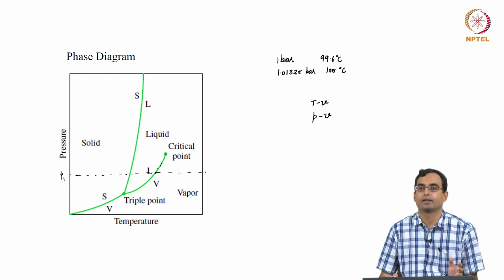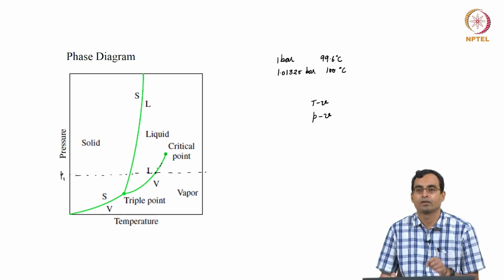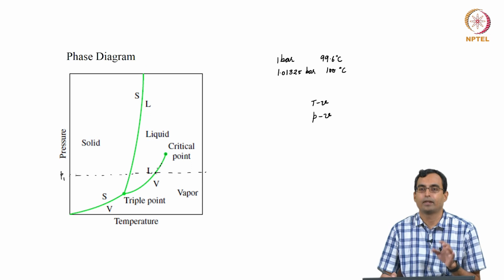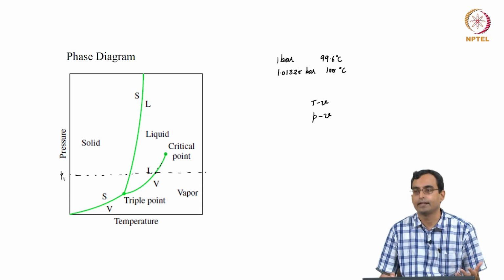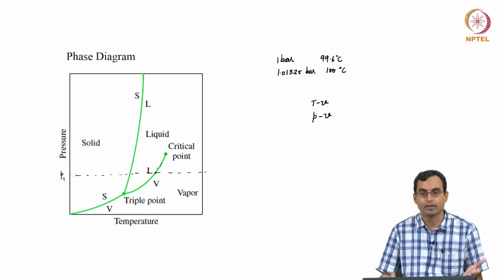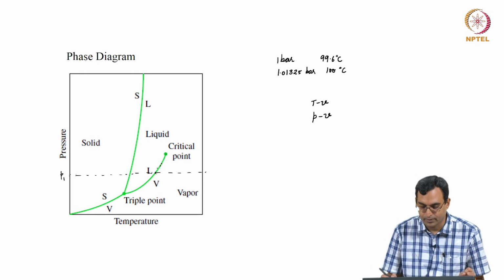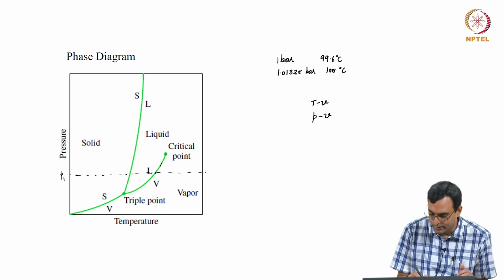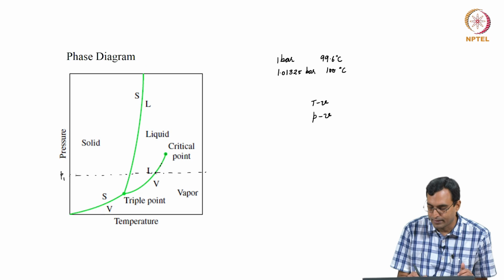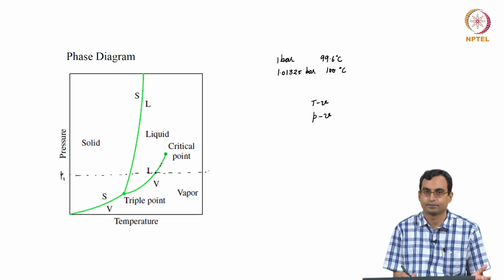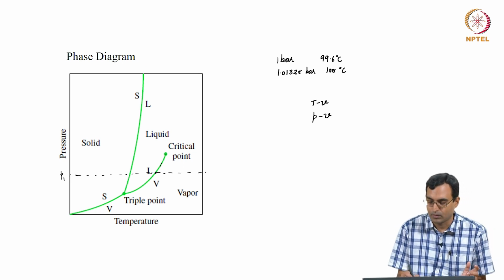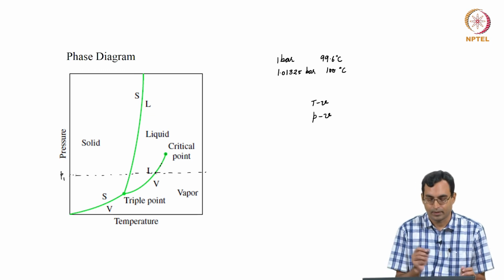This again represents a phase conversion point. So, at this point when I just reach it, I have liquid at that pressure. I am continuing to give it heat at constant pressure. What happens is that the liquid starts to become vapor. Initially little vapor is there, but the temperature is fixed. It does not change because I am doing this at constant pressure. After some time, all of it becomes vapor, and once all of it becomes vapor, the temperature once again starts to increase and I get to this side of it and I have vapor whose temperature is going on increasing. So, that is what happens if I do a process at constant pressure at this particular pressure.